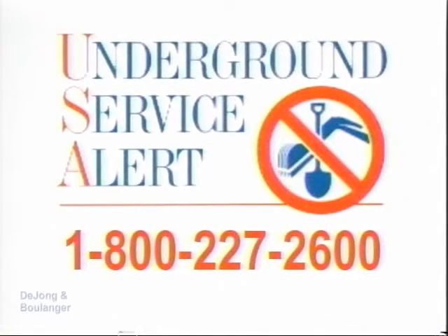In any drilling program, the first step is to check for all possible underground utilities or obstructions, and get an underground service alert clearance as required by law. No drilling should begin without this clearance, no matter where the site is. After the drilling is completed, all boreholes or piezometer installations must be sealed in accordance with state and local regulations.